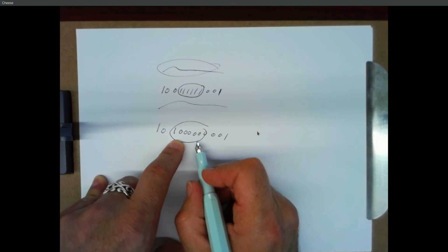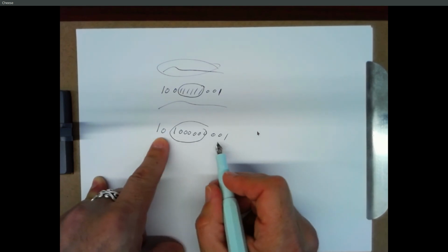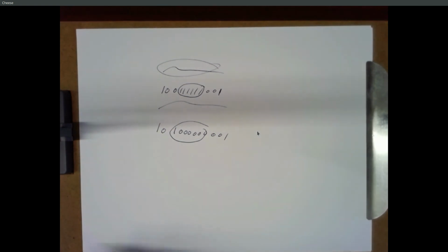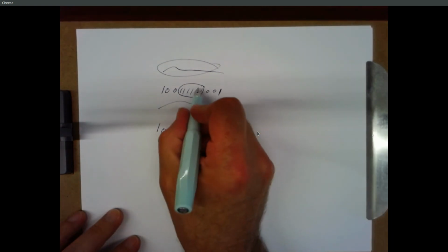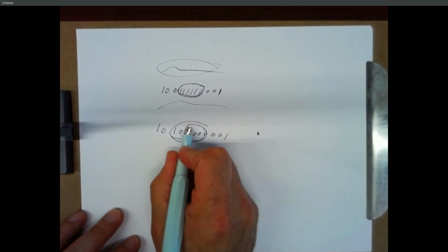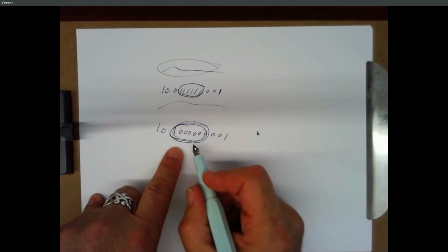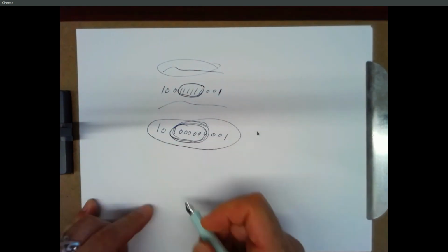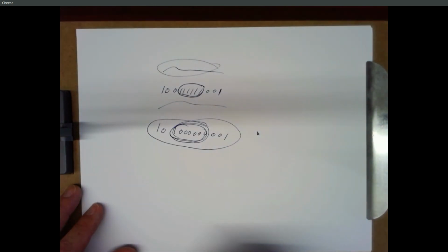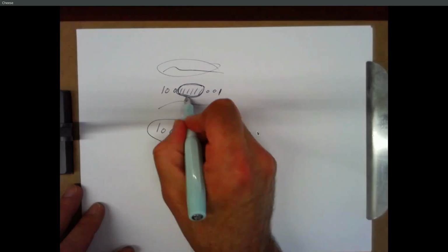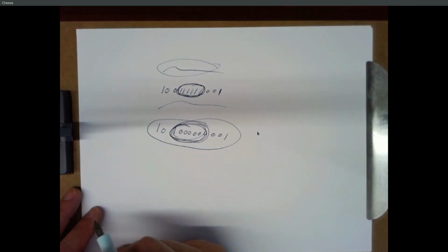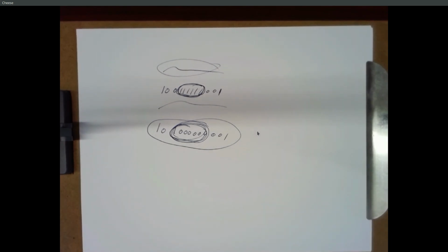This is a really easy number to multiply by because you've only got 3 1s in there. You're only going to get 3 non-zero partial products to add together. Well, our number is this. It's not this nice simple form like this. It's got a bunch of 1s, but it's almost this nice clean form. We can pretend that it actually looks like this, multiply by this number, and then just do 1 subtraction to take off 1 more of these things, because the thing we were going to multiply was actually 1 less than this. That's what Booth's algorithm builds on. And it works great if you have a pattern of 1s sitting side by side. And so there's all kinds of tricks like this for speeding things up.